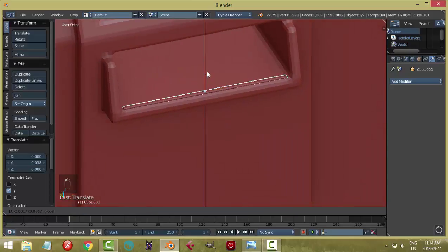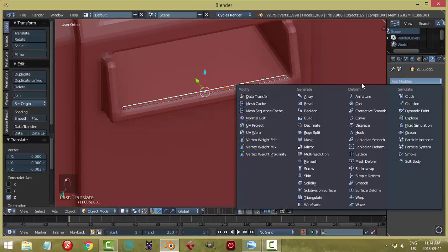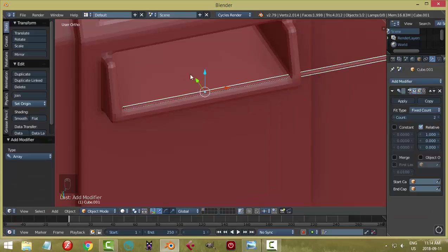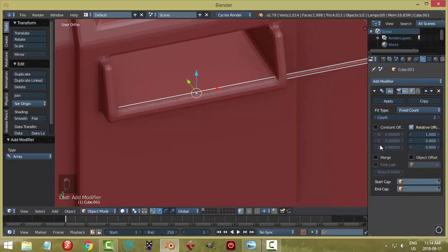And maybe we want it down a little bit further, and let's add an array. In the Y direction going back, so this is the Y here. All right, you can't really see. If I pull this out, it'll say X, Y, and Z. So this applies if we check here, but because I've got to check here, this is the value. So I'm going to tug on this till I see it going back. See it's going backwards. Get rid of the X, put that as 0.